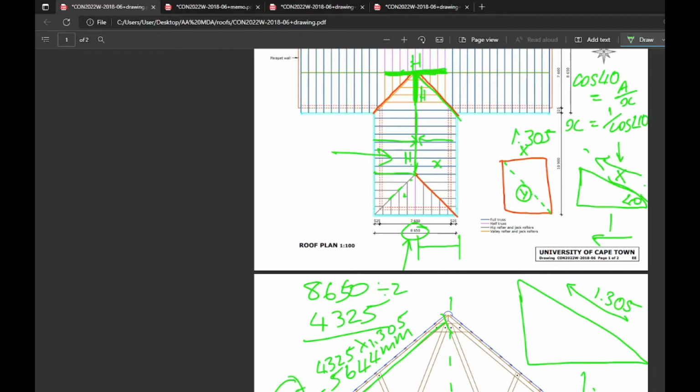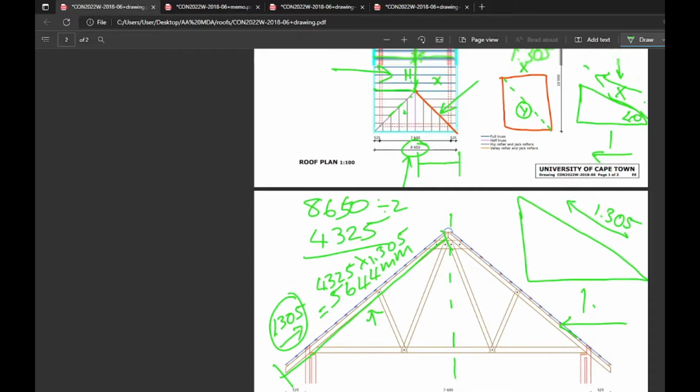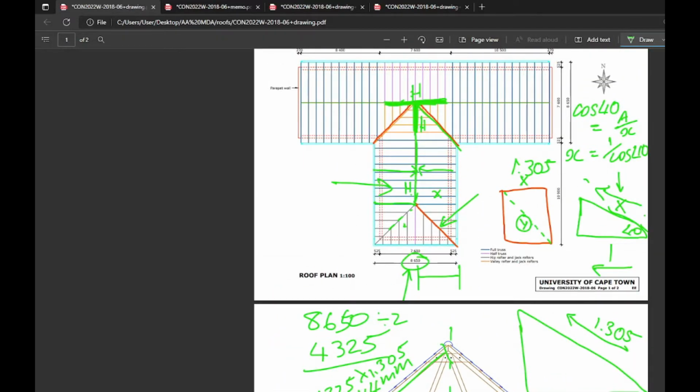That doesn't tell us this length for our hip rafter. So it's a bit easier from here, which turns out is just some Pythagoras. And it's interesting, I had to wrap my head around this. You've gone from plan, a square. Okay?